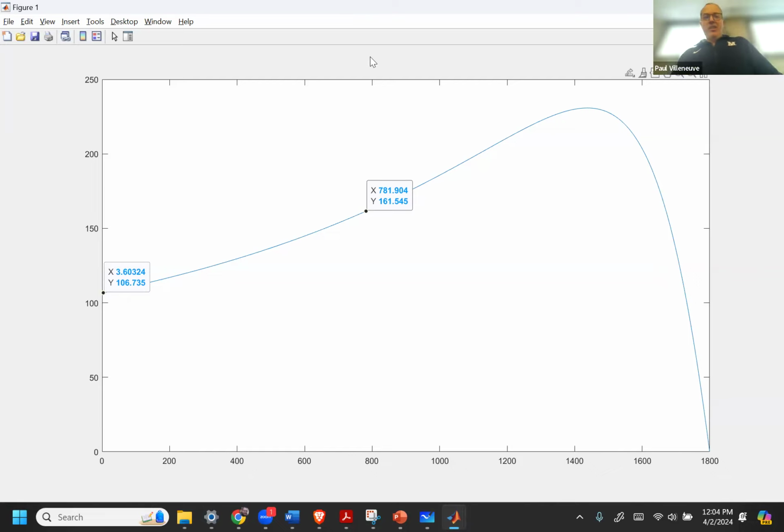Okay, any more questions? So it's going back to finding voltage Thevenin, V Thevenin and Z Thevenin. Yep, the Thevenin equivalent voltage and the Thevenin equivalent impedances. Once you have those, you can approximate what the maximum torque is, and you can approximate what the value of slip is when max torque occurs.